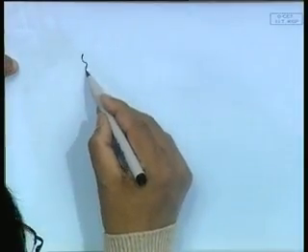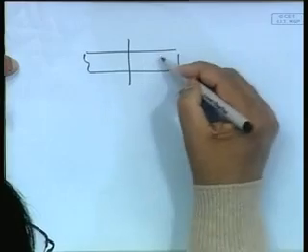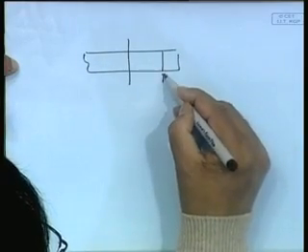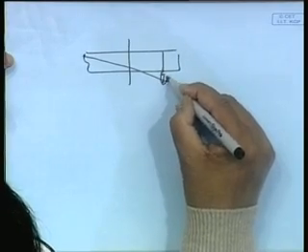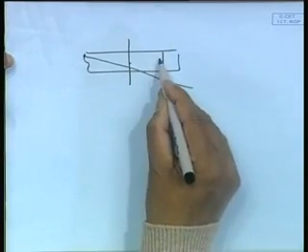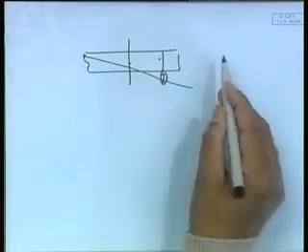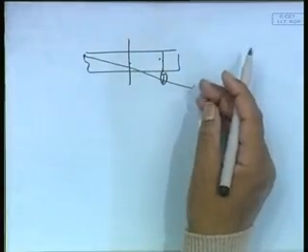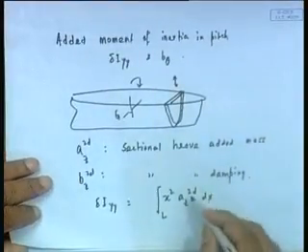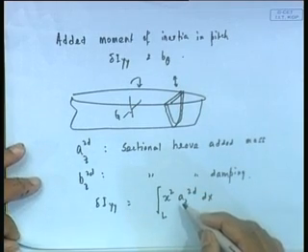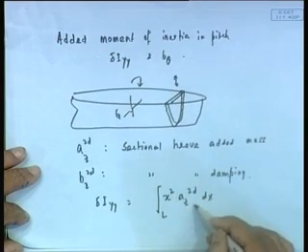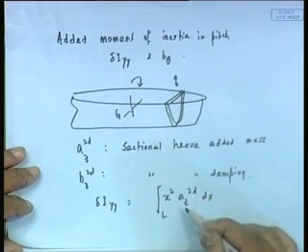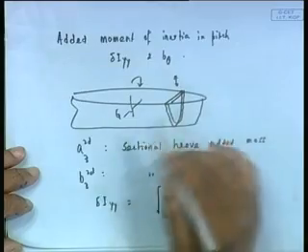I will show this picture in this form again here, because it is easier to see a two dimensional form. So, I have a section here, let us say this much is my added mass, body is rotating like that. So, what I am doing is taking the added mass times x square, integrating over it. So, you see, I can estimate pitch moment of inertia also from sectional heave added mass, and similarly the damping part.